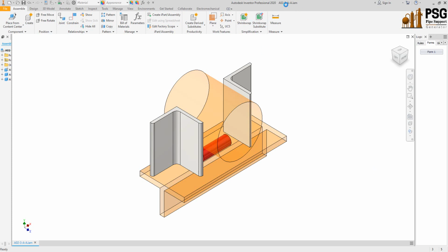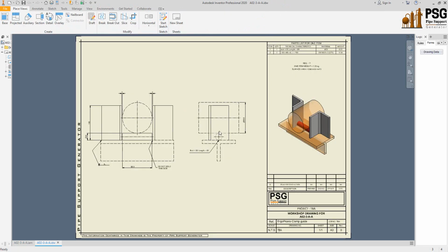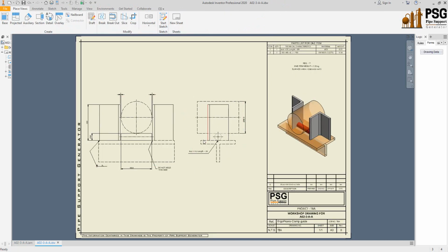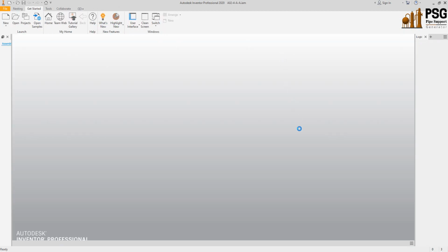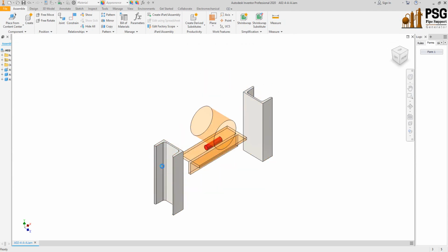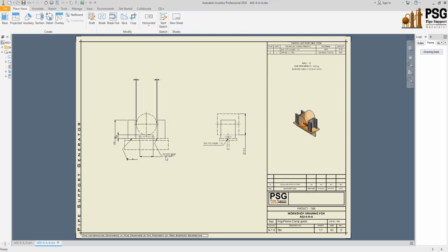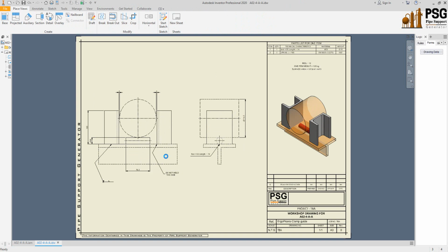As you can see here, the size is 3 inches, and according to table A and type A, the drawing will be generated automatically and the bill of material will be generated. The second support is 4 inches. As you can see, the configuration of the guide hot rolled section changed to a UPN. Okay, and the drawing is automatically generated based on that.